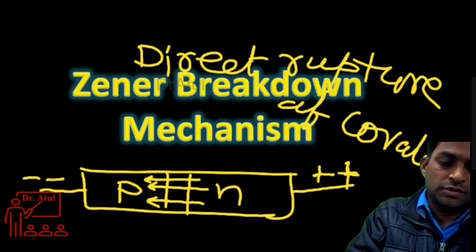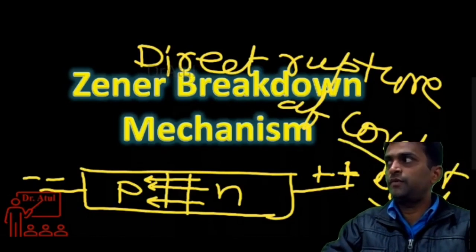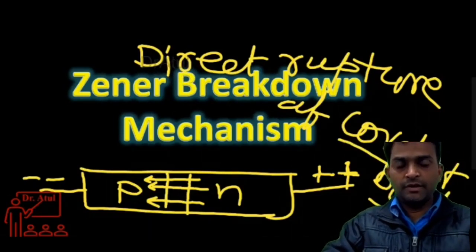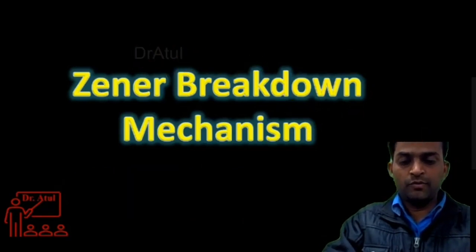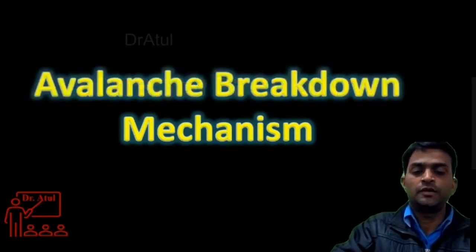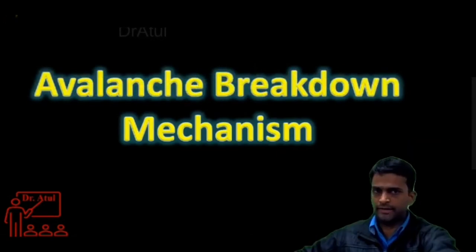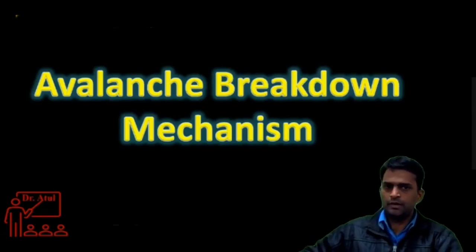So you can see the region, carefully understand the region, that this is because of direct rupture of covalent bonds. Zener breakdown, why is it happening? Because here there is a direct rupture of covalent bond. The next breakdown mechanism, which performs at relatively higher voltage, is avalanche breakdown.